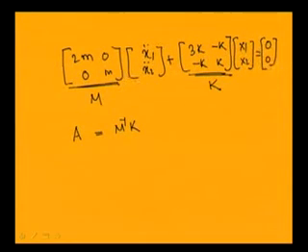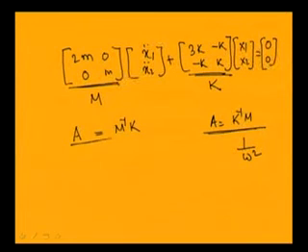So, when I write A equal to K inverse M, the eigenvalue of this will give me 1 by omega square, and when I take A equal to M inverse K, the eigenvalue lambda will be equal to omega square. So, let me proceed by taking M inverse K. So, if A equal to M inverse K, I can find this matrix. A equal to M inverse K is equal to 3 by 2 K by M, minus K by 2 M, minus K by M, and K by M.